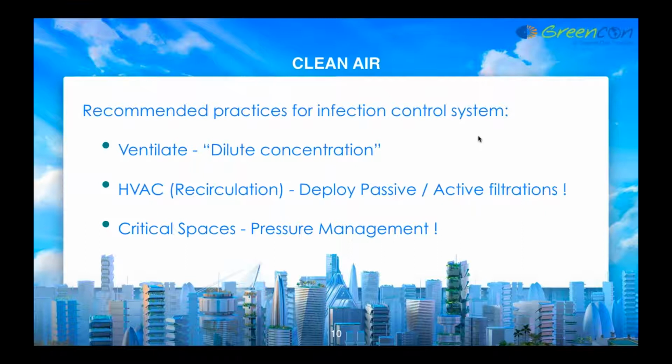The point over here is, how much is good? Is 1 air change good? Is 60 air changes good? Please understand, if you're talking of 2 air changes per hour, we are breathing the same air for at least 30 minutes without that air getting replaced. That means the contamination chances for the individual within that space could be as high as within 30 minutes if he gets in touch with that kind of particle.